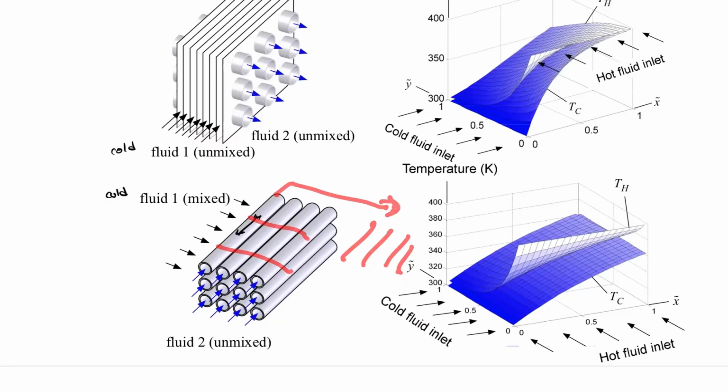So now that gets into maybe you come up with a model where you solve that first block, and then you mix the temperatures, and then you solve the second block. And you have this multi-pass type heat exchanger model, where you're modeling each pass separately in sequence. Or a lot of times, people just do empirical correlations and use that instead.